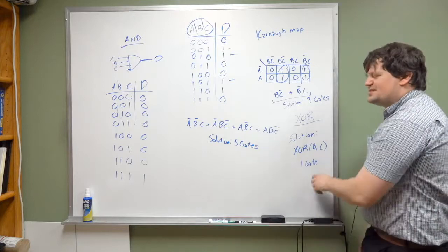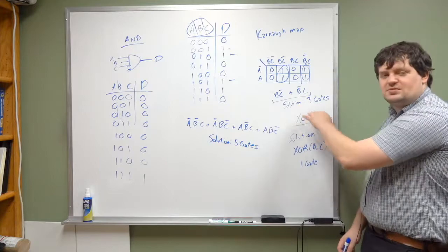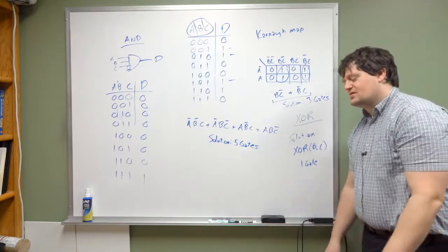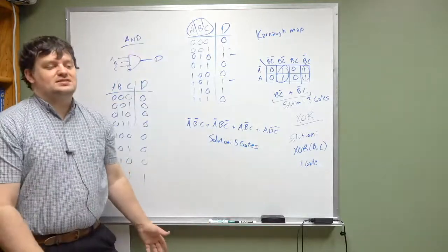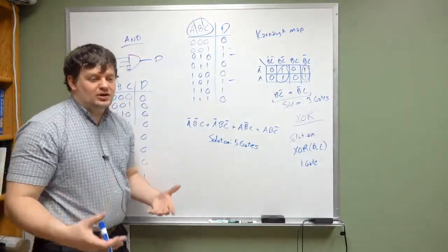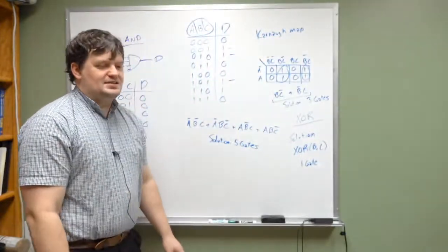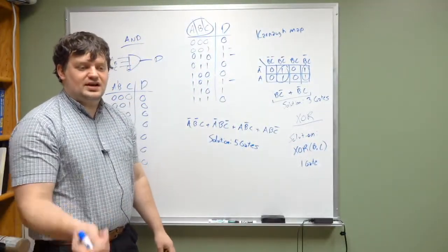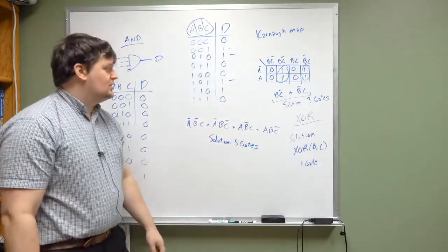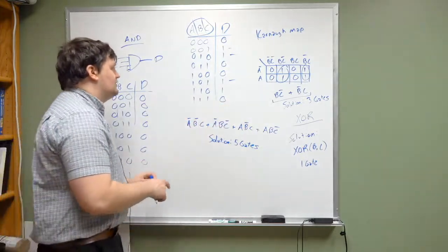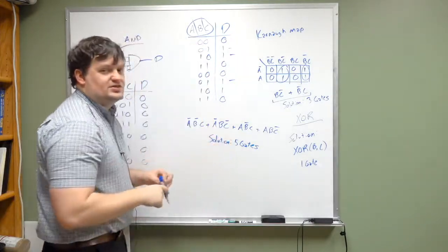And most of the time you won't be able to do that. Most of the time you'll end up with something where there's like 3 gates, 5 gates. But the reason why you do Karnaugh maps is that it gives you a whole lot more. It is kind of a don't care condition. Yes, Kenny, because it doesn't care what the value of A is. In fact, you could completely remove A, and it doesn't even care about it.